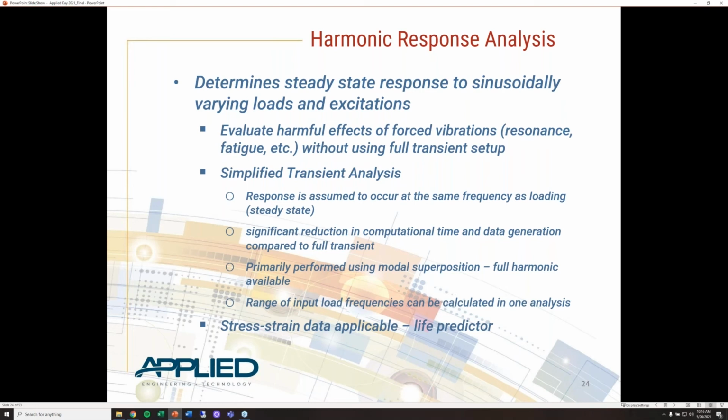Without using the full transient setup, okay? And really, this is a simplified transient analysis, and we simplify it by assuming that the response occurs at the same frequency as the loading, and this would be steady state. So our response is going to be steady state with our loading.